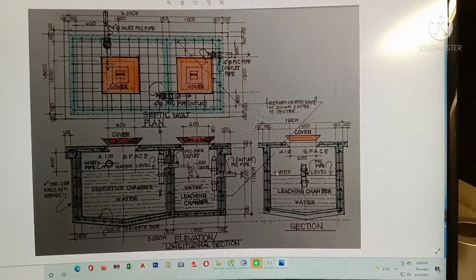So once the waste is inside the center here, it will be rotated towards the sides, keep on rotating until it is filled with water, and then it will be thrown away into this leaching. So from the leaching also, no need to have an inclination of the flooring. Just only level, because this portion here is just smaller particles, pulverized like sand already. From the biggest particle become smaller. Okay, so the waste here becomes as big as sand, right?